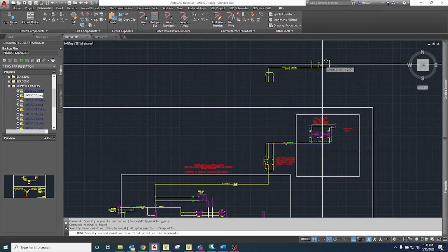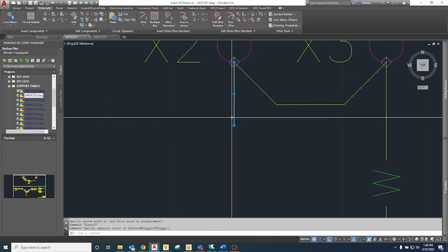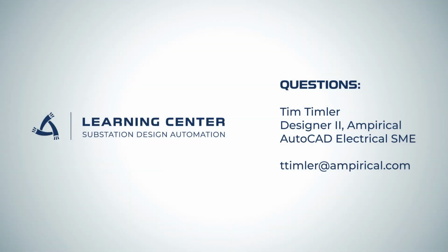This demonstration is a good example of that middle ground option that I mentioned in our April session. Tielinks are predominantly used to create intelligence in hand-drawn raster designs, but this video briefly explored how to use Tielinks to quickly create a hybrid AutoCAD Electrical schematic wiring diagram within that AutoCAD drawing. Tielinks offer an incredible amount of creativity with the ability to add data while also being discrete. You may even explore adding them directly to vendor drawings to create data on drawings that you were already including in your design package anyway.